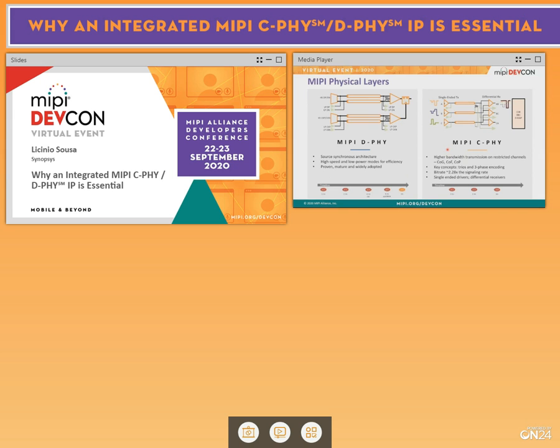Things like chip on glass, chip on film, or chip on plastic. The key concepts are trios and the three-phase encoding, and all the rules on top of that in terms of encoding and mapping. With that, the bit rate is approximately 2.28x the signaling rate. So you're effectively sending more bits per transition, more information per transition.